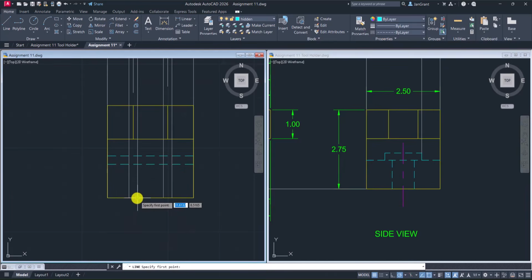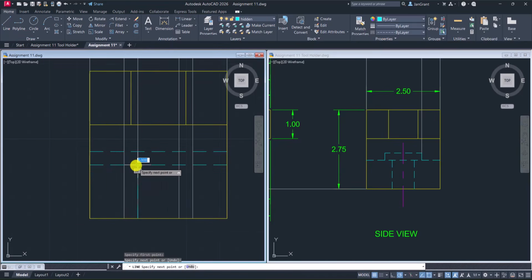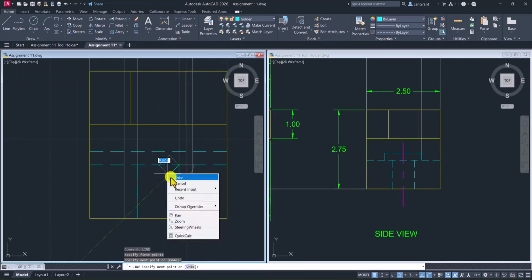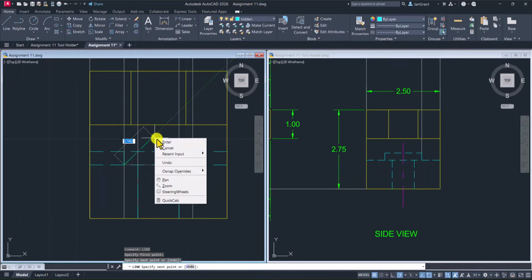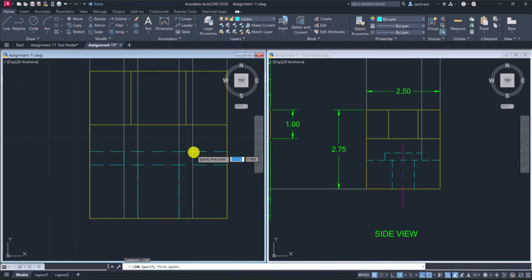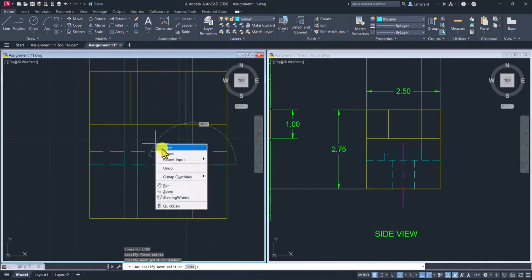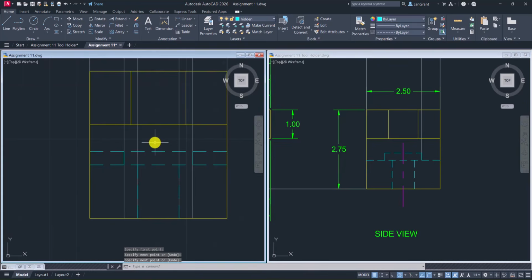Now be careful here because I'm drawing the hole that goes from the bottom up to here. And I'm drawing this other line that goes up right there, the hole. And then the only other ones I need are the ends of this boss, like right there, that one, and this one. At this point, I think you're ready to delete some lines or trim them. Actually, I can delete these 4 gray ones. Sometimes I can just turn them off as well.